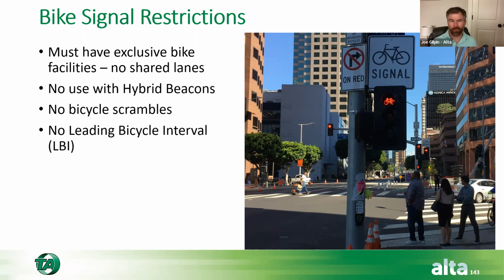So that's an issue. The current guidance in the proposed rulemaking for the MUTCD for the next version does not include any allowance for a permissive leading bike interval. However, there have been FHWA experiments both in New York City and in Austin, Texas, that looked at dozens of intersections, and they used flashing yellow arrow and leading bike intervals and found pretty good compliance and pretty good safety out of that. So the nice thing there is you're not having quite as much of a delay implication to using the bike signal. You're getting some safety benefit, but you're not getting all of the penalty.